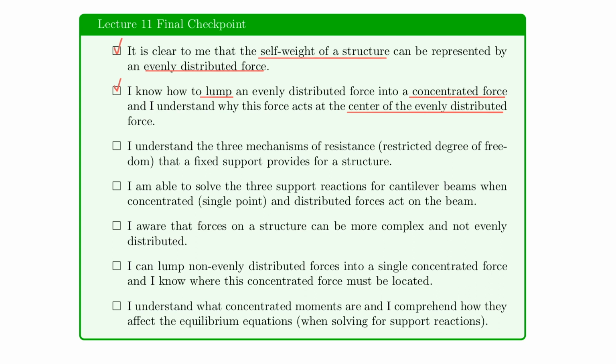Then you definitely learned about the resistance that a fixed support really provides. So let's make sure that we understand the fixed support. And last lecture we called that restricted degrees of freedom. And today we use that to clarify that all three types of equilibrium are balanced at that one location, at the fixed support.